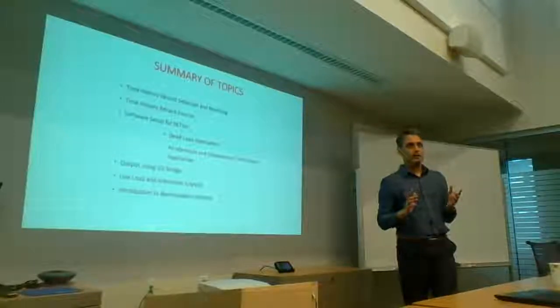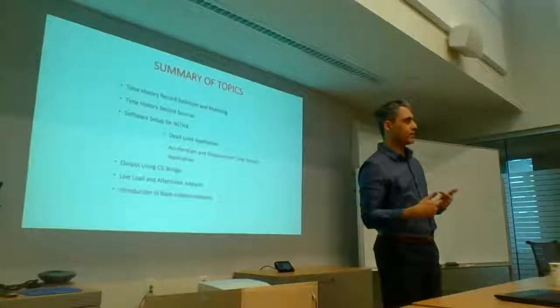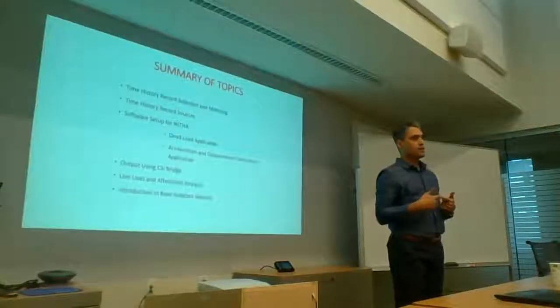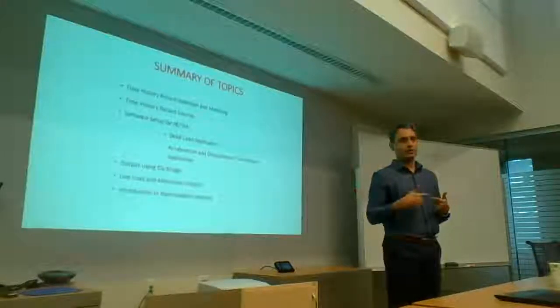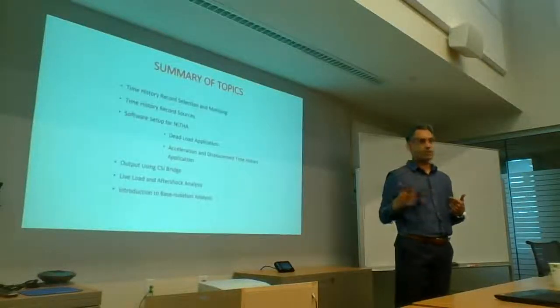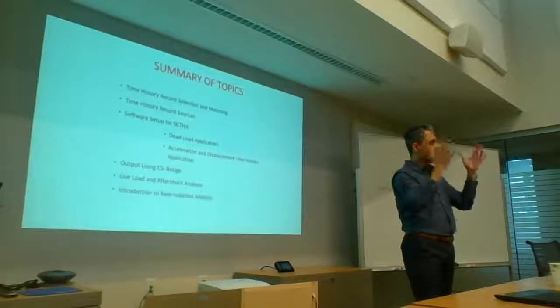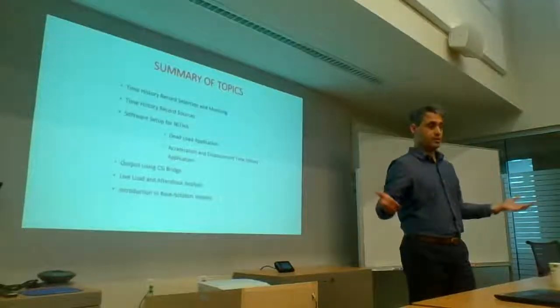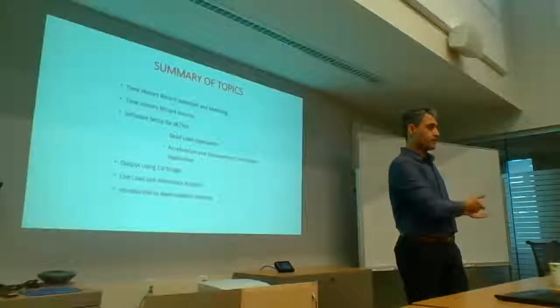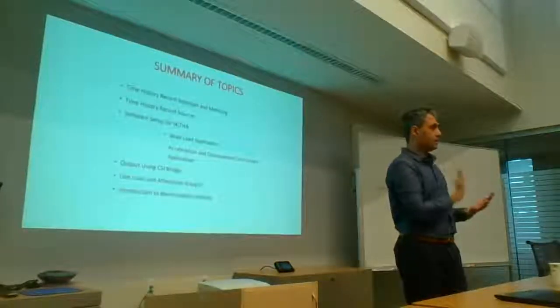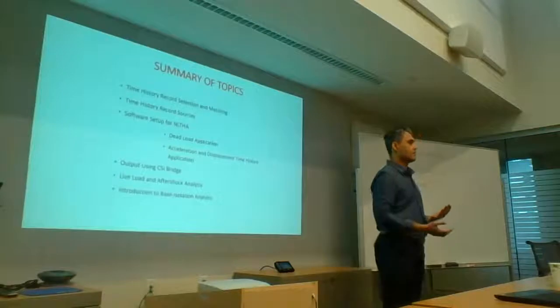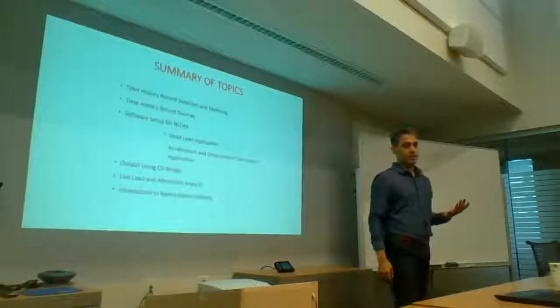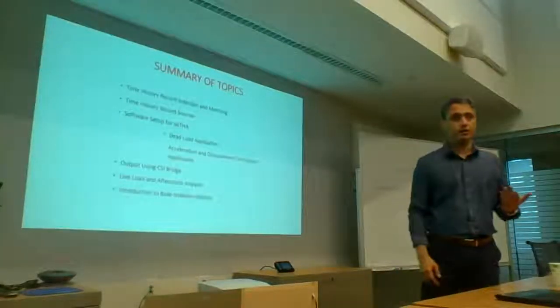When you look at the seismic hazard deaggregation, it's an issue with longer period structures. So when you're looking at 2 seconds, 3 seconds, so longer bridges, taller buildings, it's going to have more of an impact. But all the 1 or 2 story masonry buildings in Victoria that are very non-ductile, those are going to get hit more by a shallow crustal event.